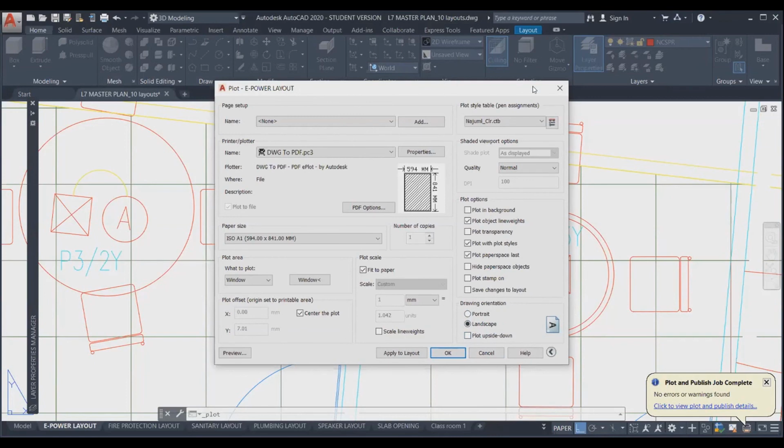So this is the way to assign the pen assignment. This is more advanced. No need to think too much about it now. When you go to the drafting department, when you do the AutoCAD real workflow, that time you can try. If they want, then only you can try. Otherwise, you can choose grayscale, monochrome, or ACAD. These three will be common. They will be in the pen assignment list. You don't need to create anything. If they want to customize, then only you have to create these things. Otherwise, you choose it, then apply, preview, print, then take the printout and hard copy.